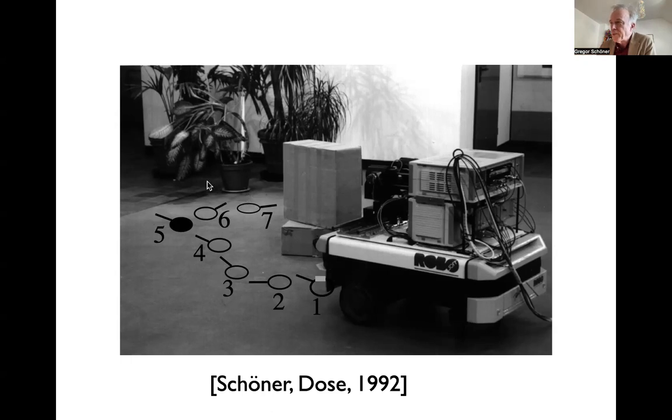And there's some other obstacles. And the target was here only known by dead reckoning. That is, this vehicle had good shaft encoders and was able to predict where it is. And so it has a map of where it is. That's the other problem of navigation: you know where you are and where you're going. I'll come back to that. So here it was solved trivially in that the system had some Cartesian map and was calibrated by the initial condition. This was, of course, a map that got worse and worse in calibration as you moved through the plane, and therefore it reached the target.